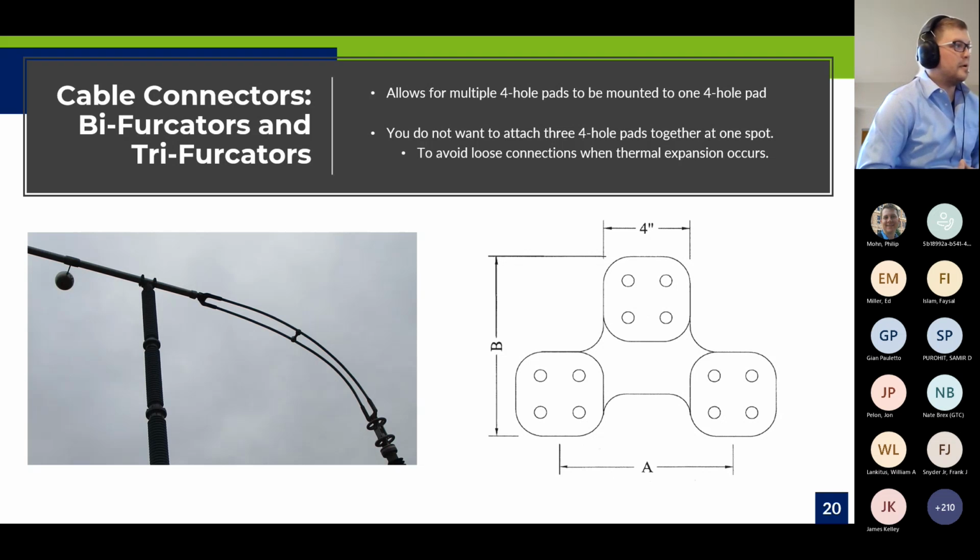Another topic I want to just cover real quick is bifurcators and trifurcators. This would be the example of if you had this bus run, and then you decided two 1590 ACSRs is more efficient than doing one larger conductor, but you bought 2 individual cable to flat terminal pads. You could essentially lay this 4-hole pad on the cable to flat connection for the bus to flat connection, and then put your 2 terminal single barrel